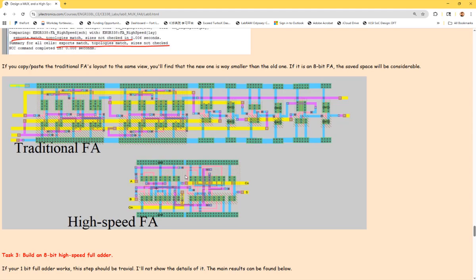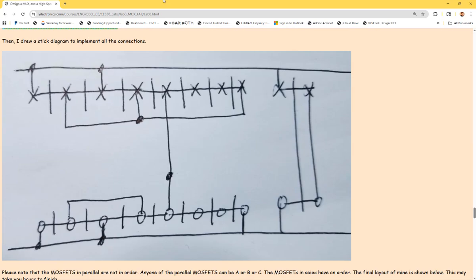However, you won't be able to handle billions of transistors and try to simplify logic over there. It's impossible and unnecessary. So they directly use the Cadence tools to synthesize, and it won't be optimized. So all these will be gate level logic circuits formed by Cadence. There are billions, sometimes 100 billion transistors. It's not optimized. But when you are doing mixed signal design, you manually optimize it. Okay.